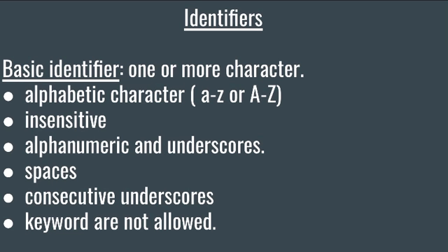It can contain alphanumeric characters and underscores also. It cannot contain spaces. In this basic identifier, no two consecutive underscores are allowed, and also no VHDL keywords are allowed.